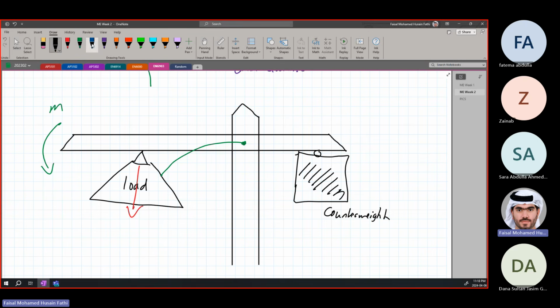So instead, what we want is for it to be balanced. We want the total moment around all of this, or we could say the sigma moment, to be equal to 0. The sigma moment about this point, let's call this point C. About C, we want it to be equal to 0. In other cases, we call this equilibrium. And how is that usually done in cranes?